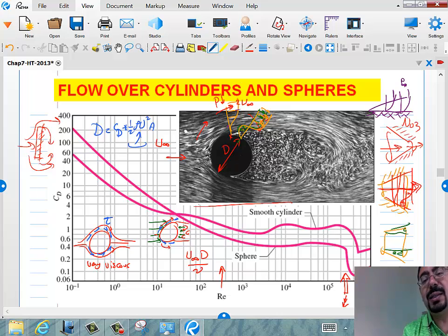So now if we look at this cylinder as two parts, this part is as if it's going through, what is that? This part? Nozzle. And as a result, one should expect the velocity here to be much bigger than U infinity. The velocity at this place is almost twice as large as the free stream velocity. So if the air is coming at 10 meters per second, here it will be 20. The pressure will end up being lower than P infinity.